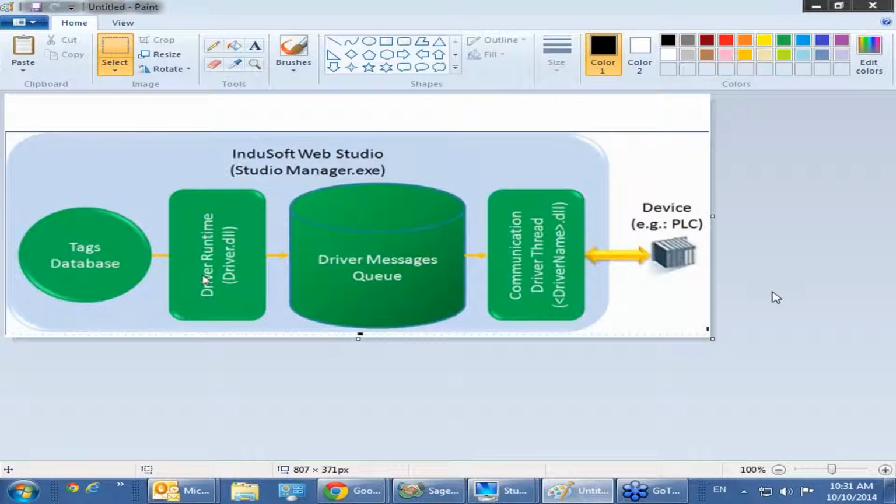Okay, describe the COM port configuration using USB. This particular module, the ZT2551, doesn't have a USB port. When I mentioned the 7561 type converters, these have a USB port which you can connect to your computer, and they also have RS-232, RS-485, and RS-422 type ports on the bottom. So you could plug one end into your computer with the USB port and then use RS-485 or RS-232 wiring to go to your serial device. This is the kind of device you would use to connect your computer to the ZT2550 or 2551, for example.